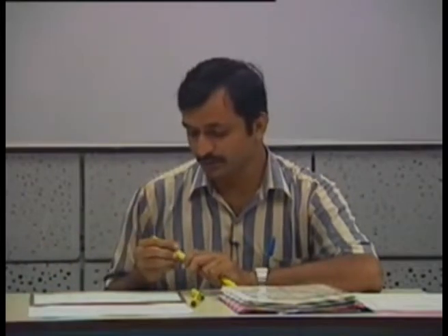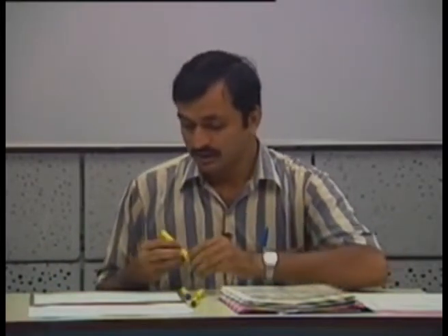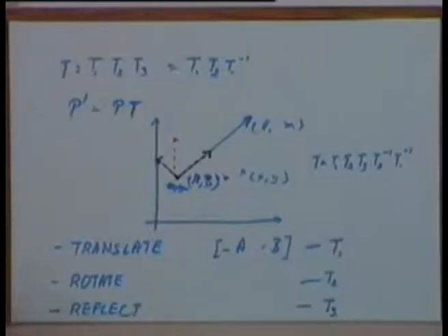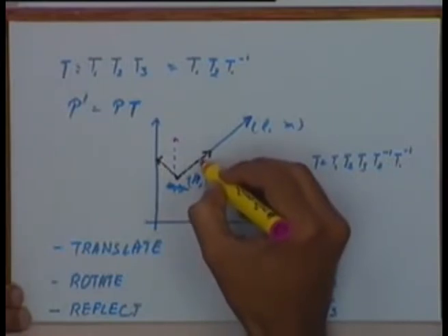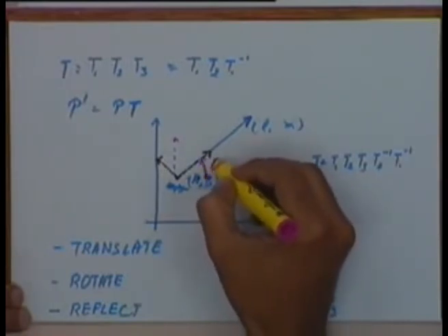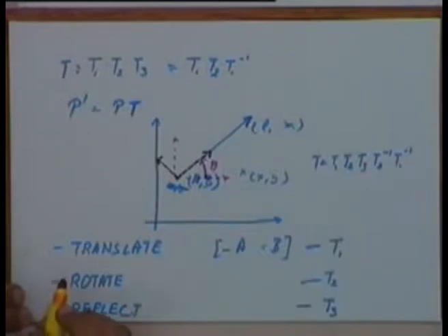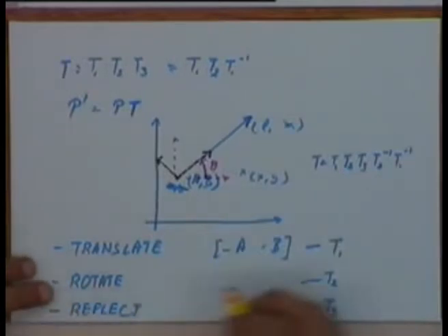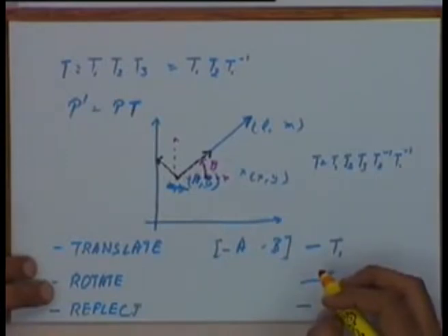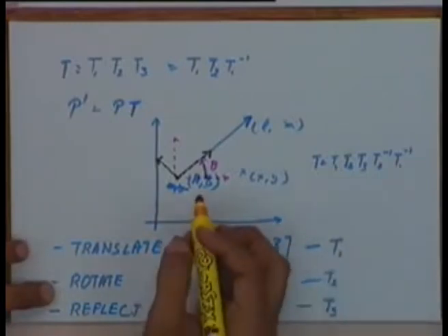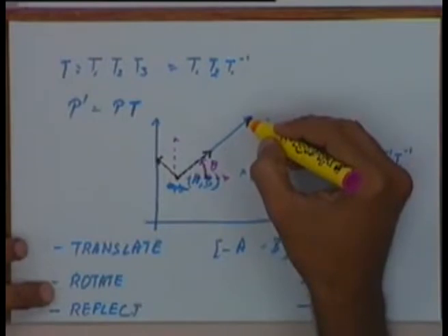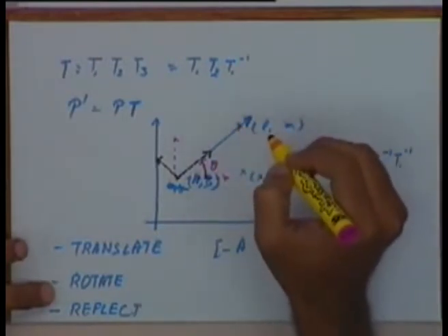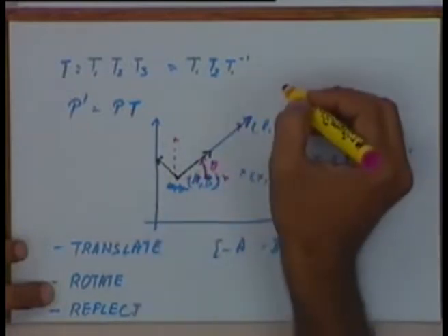Only one thing you should be careful about is in step 2, when we are rotating the axis, let's say this angle is an angle theta, we will have to write the transformation matrix for minus theta. Because what we want is that this direction should now become the x-axis. So a point on this axis will be a point on the x-axis.